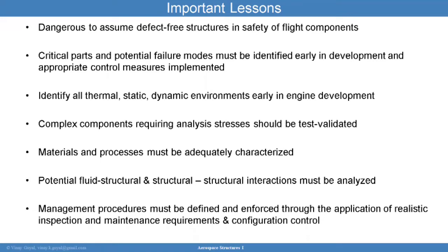For example, if I forgot that this particular piece of structure is going to experience 300 degrees F, and I only design it for static and dynamic loading, and that 300 degrees F causes a strength reduction in the structure, that is a major problem that needs to be addressed.